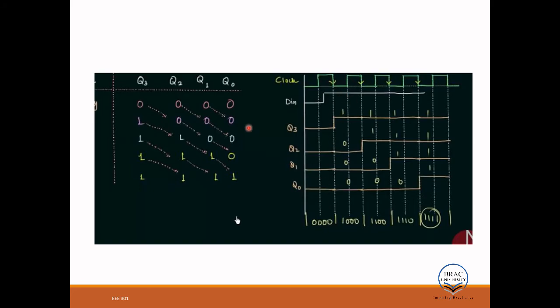So for this one again, it will be changing state at the clock edge here. So 0 becomes 1. And at the next clock edge it will change its state, and for input 0, output will be 0. Okay. So if you look at here, 1 1 1 1 1, so it's creating a clock. That's why this ring counter is forming a ring kind of structure.